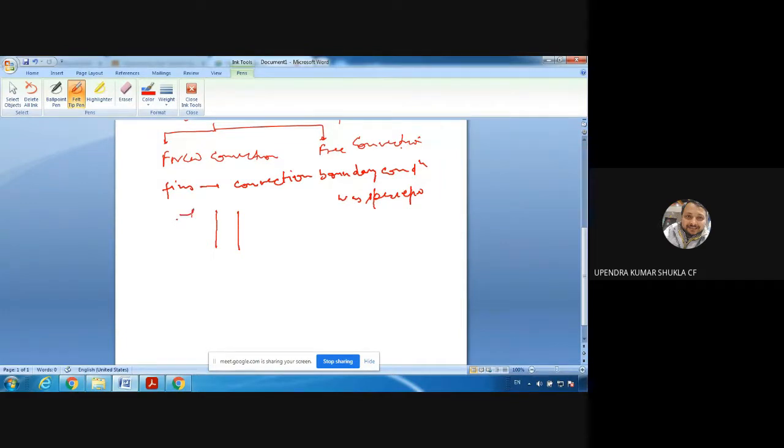On this side suppose fluid is there, and on this side fluid is there. So suppose hL is the left side heat transfer coefficient and hR the right side heat transfer coefficient. This is the solid. Then I told you the temperature in this direction, then this solid, and then this heat transfer. There are several resistances: convective heat resistance, then solid heat resistance, and then again convective heat resistance.